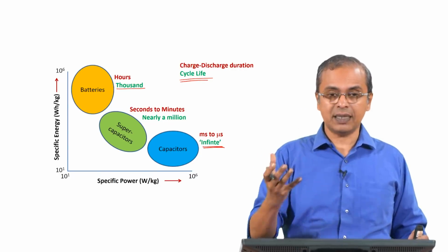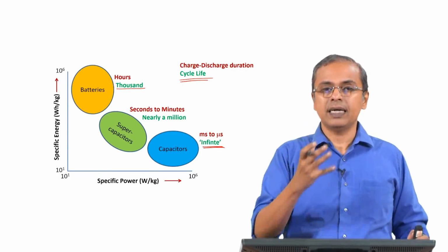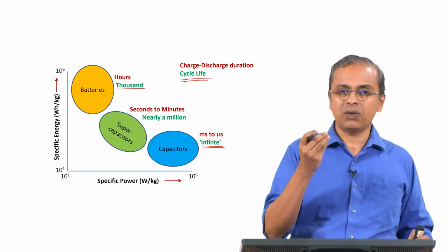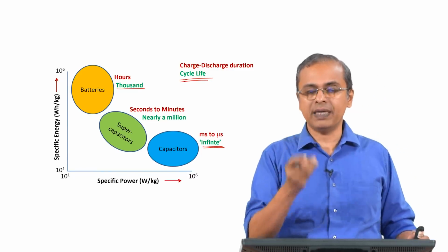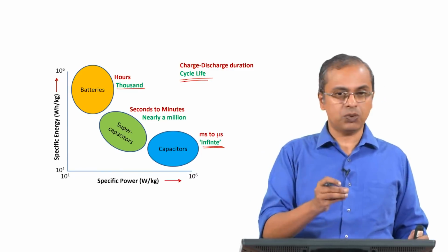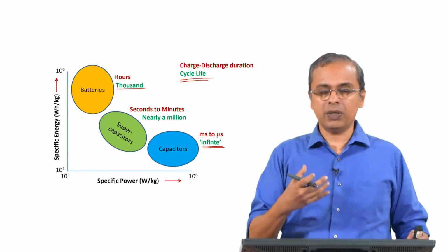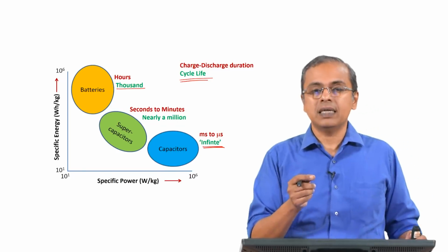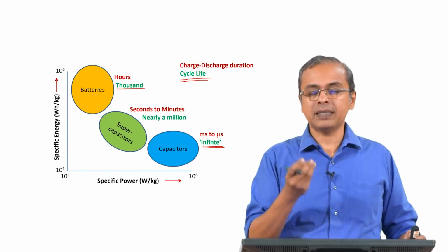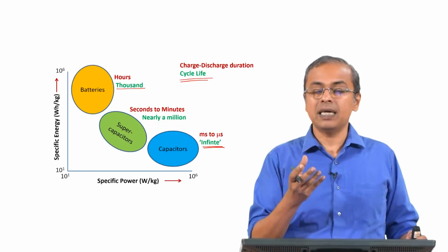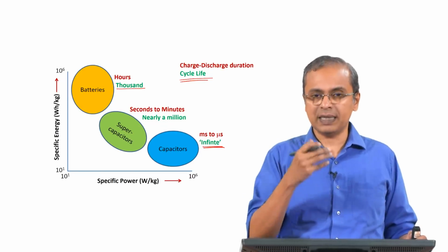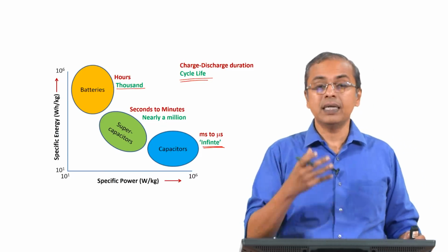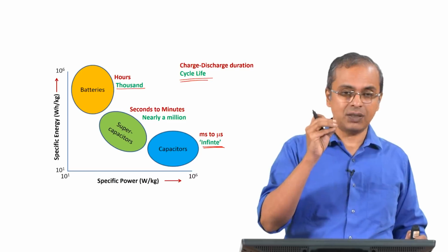So, one reactant becomes some product, and in terms of a phase, one phase becomes another phase. Each phase has a different specific gravity, and so its volume will be different. So, invariably if you look at battery electrodes, even though you do not see it externally, internally the dimensions of those electrodes could be changing. They could be swelling, they could be getting compressed, etc. There is a lot of structural change happening at the level of those particles, at the crystal structure level. That puts a lot of stress at that size scale.